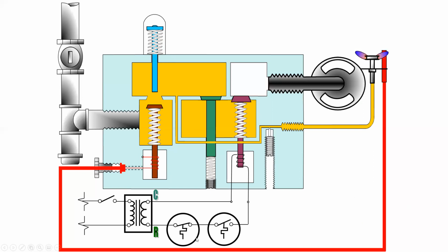Okay, so now what we're going to do is energize the electrical circuit here. And then again, we're going to focus on the thermostat, which is on the right-hand side. So let's close the disconnect. And now let's call for heat by saying the thermostat has called for heat in that the room is too cold. So as the heat drops in the room, this will contact the second side of the thermostat terminal, and what will happen is the main gas valve electromagnet will energize.